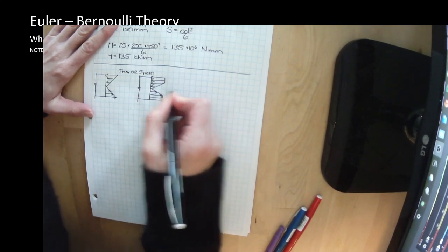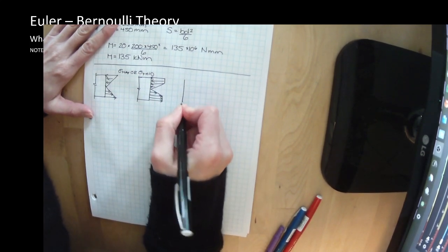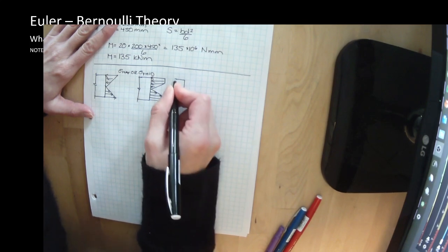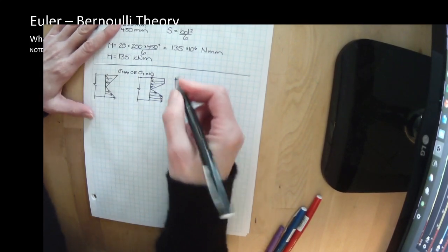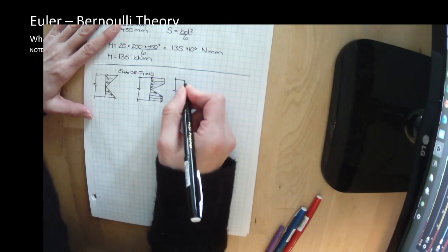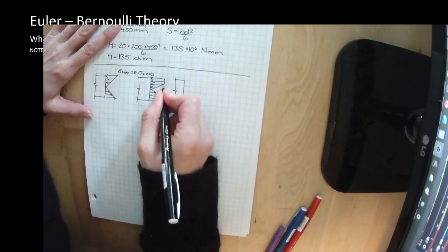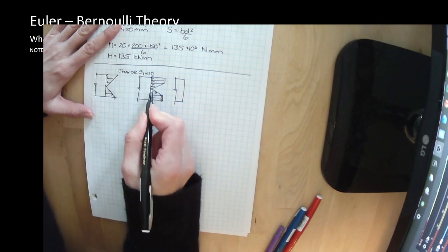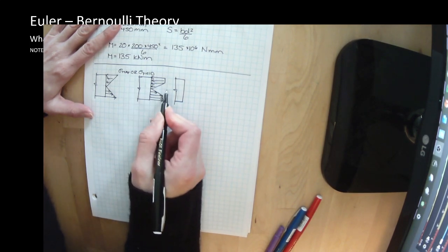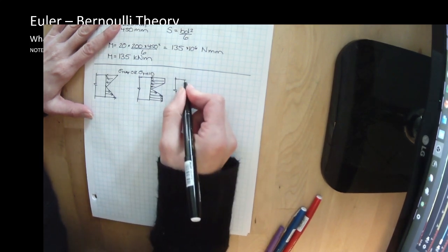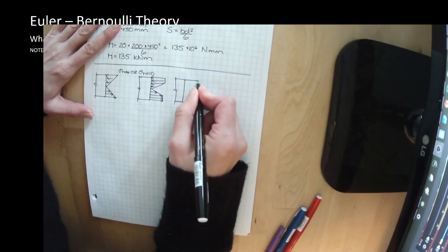And maybe we go just a little bit beyond that. We bend it just a little bit more. We know we're pushing our luck here a little bit because pretty soon the whole thing is going to start to see large scale deformation. What if we did it a little bit more? What if we came down to just a hair shy of the neutral axis, about to see that maximum stress profile?